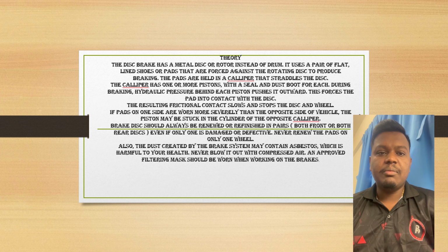Also, the dust created by the brake system may contain asbestos, which is harmful for your health. Never blow it out with compressed air. An approved filtered mask should be worn when working on the brakes.